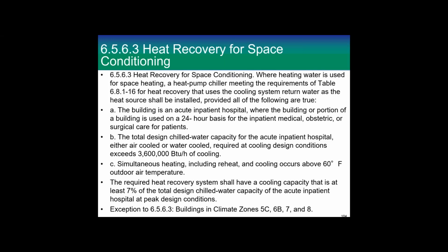So this is for an acute inpatient hospital. That's a 24-hour basis, inpatient medical obstetric, this kind of regular hospital. The total design chilled water capacity is either heated or cooled required. A cooling design condition exceeds 3,600 BTUH of cooling, so a big system. Simultaneous heating and cooling occurs above 60 degrees outside air temperature. The required heat recovery system shall have a cooling capacity of at least 7% of the total design chilled water capacity.